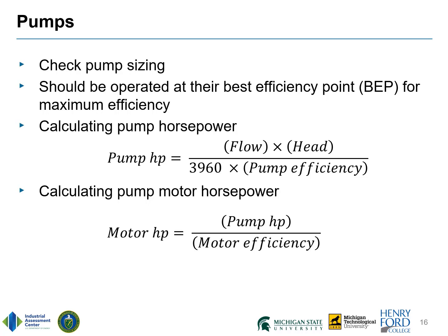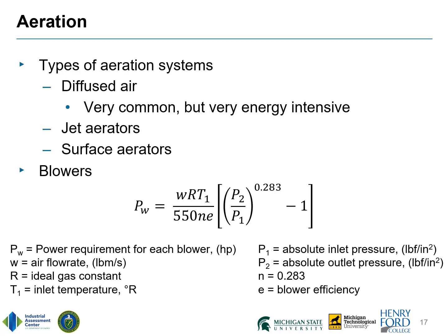Pumping contributes to the energy profile for water treatment plants. There are many different types of pumps, and a separate course would be needed to cover all aspects of pump selection. However, during an energy audit, checking the pump sizing will be useful. Pumps should be operating at their best efficiency point for maximum efficiency. It is assumed that the reader is familiar with how to read a pump curve and how to use pump affinity laws.